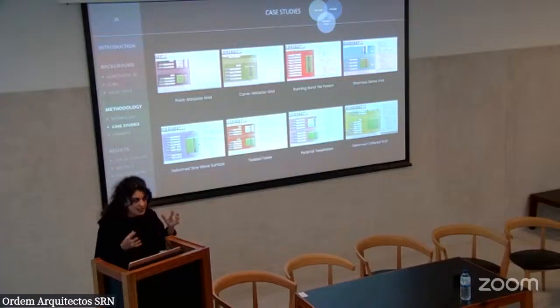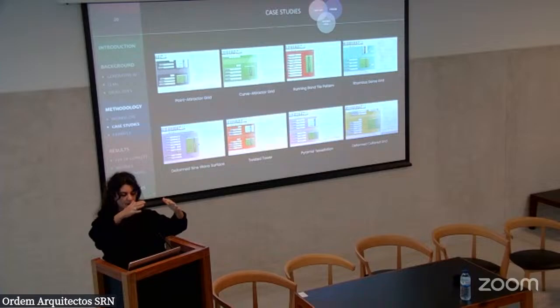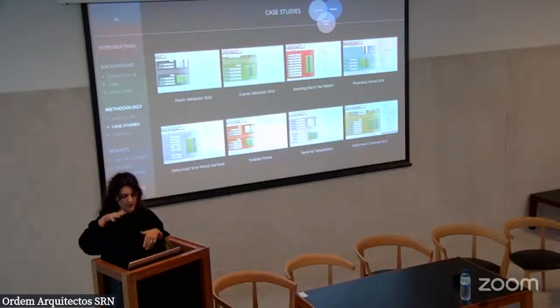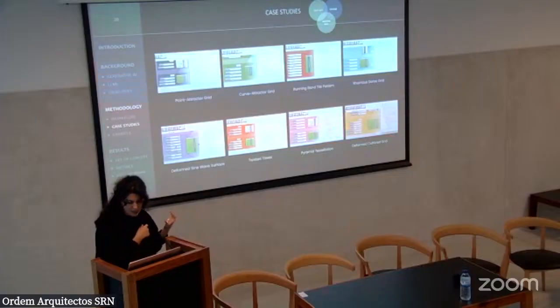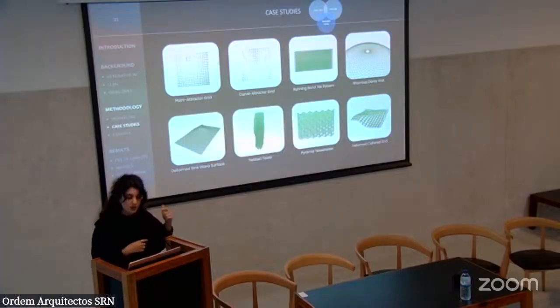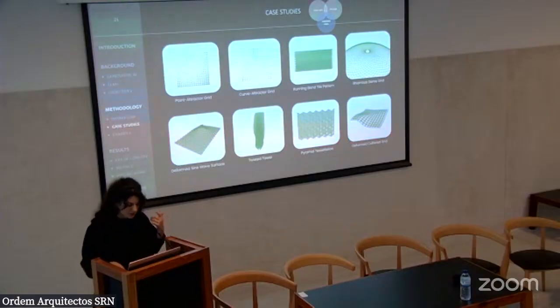This means that instead of building a series of components, you just have the Python directly in a code snippet, and you paste it into a Python Grasshopper component. In each of those case studies, we managed to get not only the geometry that we initially had, but a parametric model where you can change the parameters and get various variations upon this initial reference image.